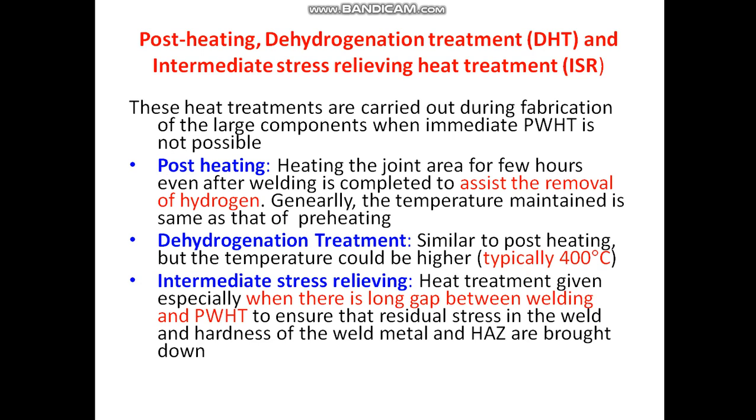The third is intermediate stress relieving. This treatment is given especially when there is a long gap between welding and post-weld heat treatment, to ensure that residual stresses in the weld and hardness of the weld metal and heat affected zone are brought down.